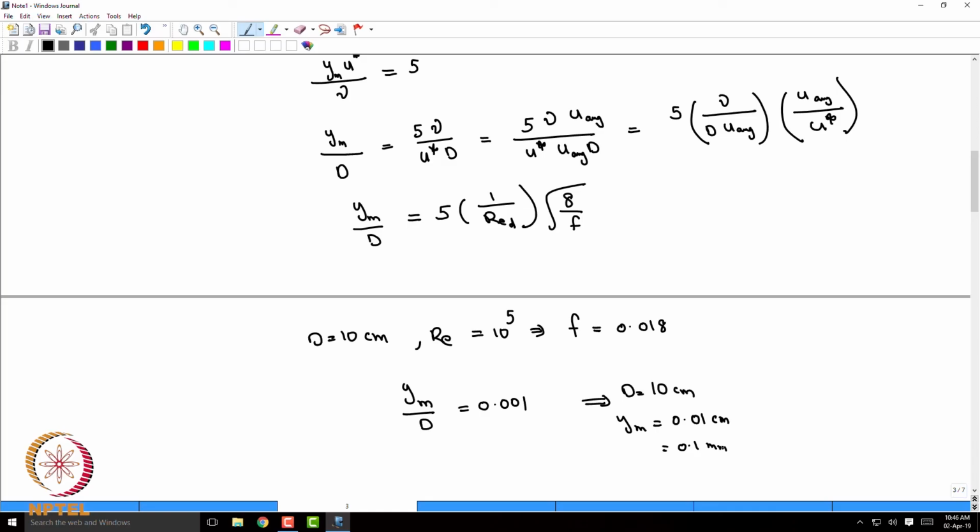Yeah, so because it affects the wall layer, the other layers sit on this layer, because of the continuity. For example, you need to maintain some stress balance that will get disrupted. So the entire thing will get disrupted. In fact, the log layer will remain as a log, but the arguments and the constant, everything will get changed. Therefore, the friction factor expression that you have gotten should be relooked at in the context of a rough pipe.